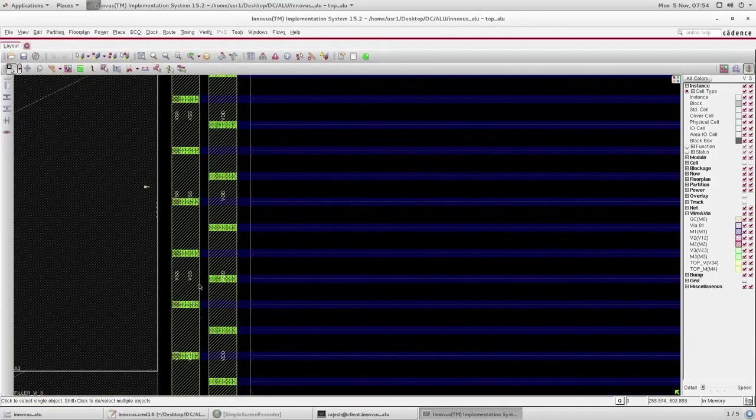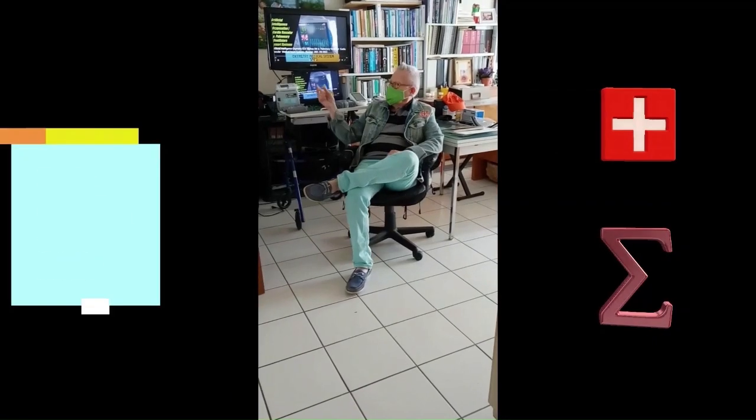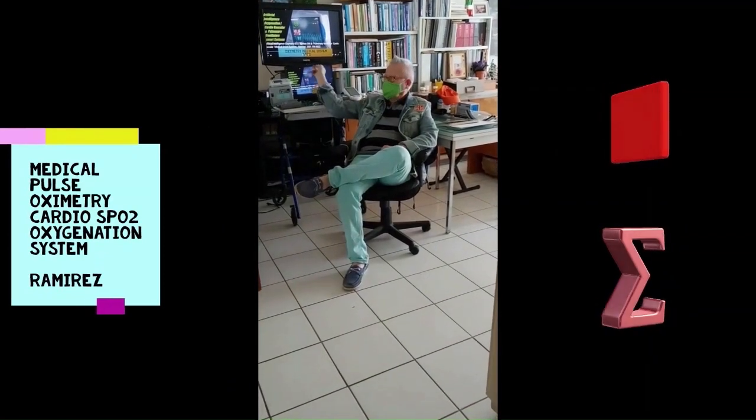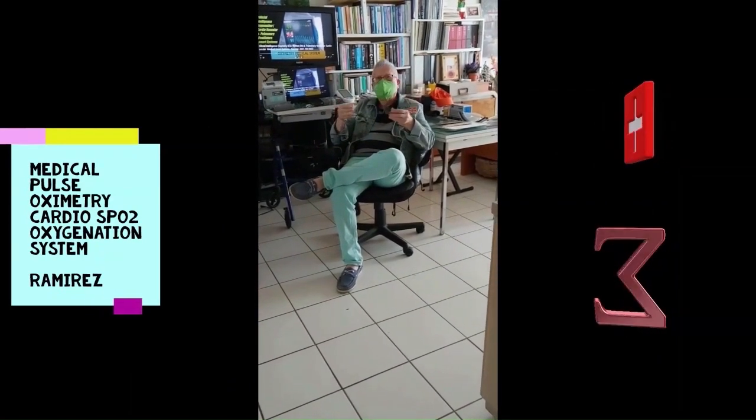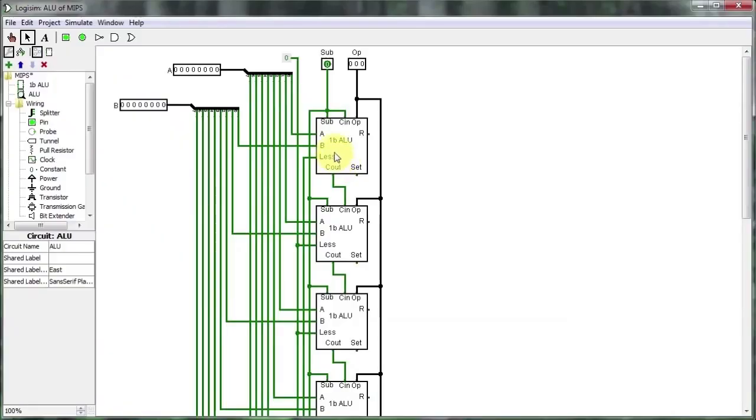Eight, legalize placement. Then generate the new timing constraints for wiring on the basis of a timing analysis done using the actual clock tree and wire load and RC delay values derived from the final placement. And then finally, perform routing.